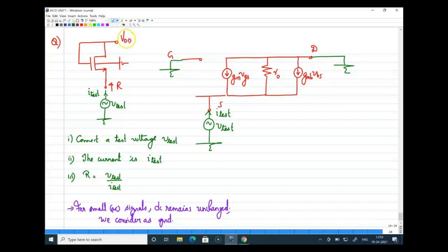All right. So what I did is I replaced the MOSFET with the equivalent circuit. Then I am making sufficient changes to find the impedance at the source. One more thing I want to mention: this is plus minus, and this plus minus is the VGS voltage. But now I want to write a relationship between VGS and Vtest, because ultimately what I want to find is Vtest by Itest. If the expressions contain only Itest and Vtest, that will be very easy for us to analyze further.